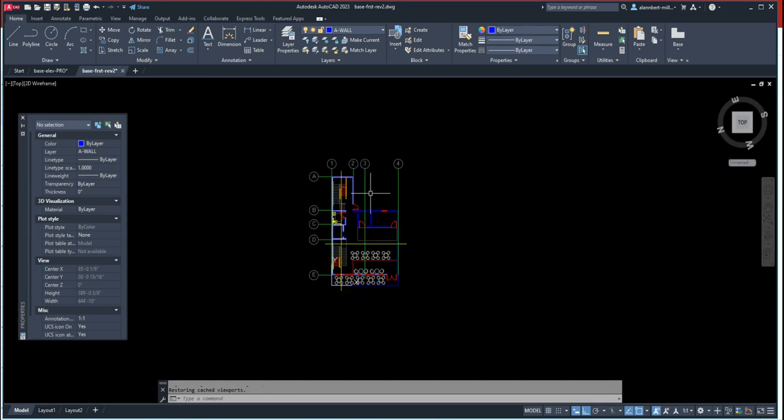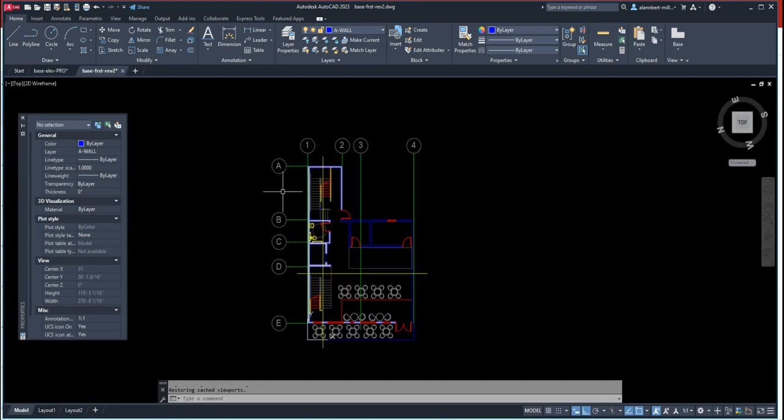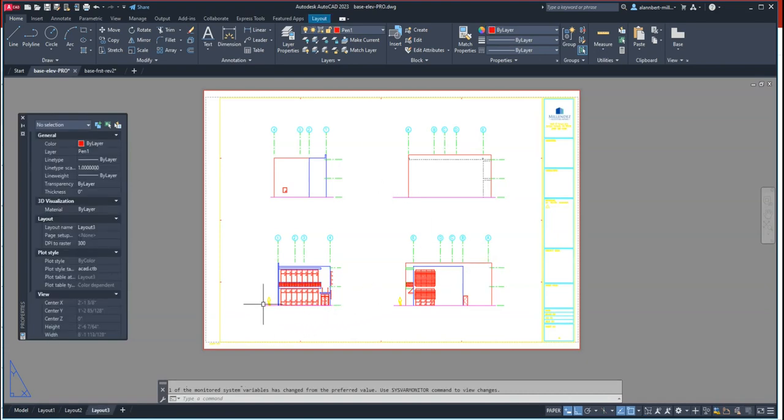We don't want to see these on a floor plan, but we have to put it somewhere so that we can properly identify that grid. We assign this on paper space, so that's why we didn't do them until now. The next thing that we need to do is probably put in some drawing titles. So this would be the front elevation, the right elevation, the rear elevation, and the left elevation. Okay, so front, left, rear, right. So sometimes that can be confusing because which one is the front of the building, which one is the rear, the right side, whatever.